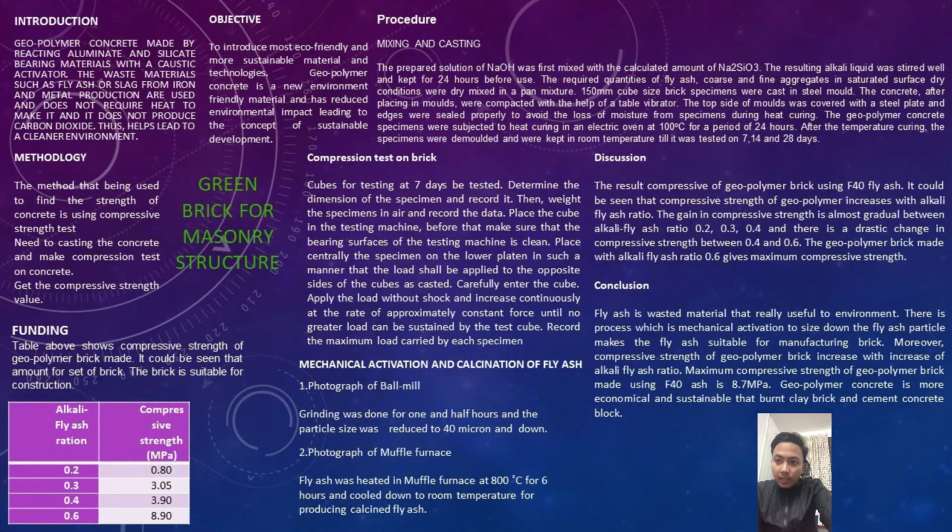For the cube to be tested at the 7th day, determine the dimensions of the specimen and record them. Then weigh the specimen in air and record the data. Place the cube in the testing machine.